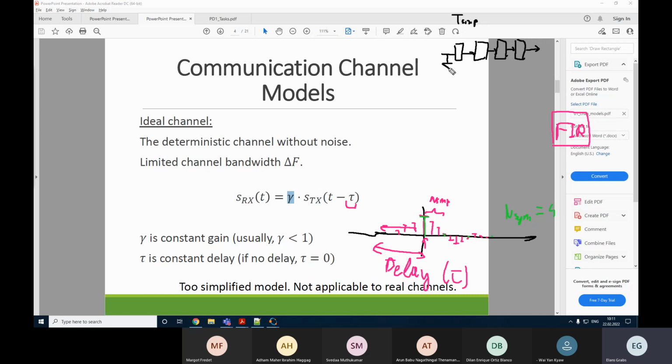And here we have multipliers that multiply the signal with exactly our values of the impulse response. We can say this is H0, this is H1, H2, H3, and for example H4. In order to get a linear phase frequency response, H0 must be the same as H4, with either plus or minus sign. Similarly, H1 must repeat H3, and in this particular case, H2 is the center of symmetry, which can be either 0 or some specific constant value.